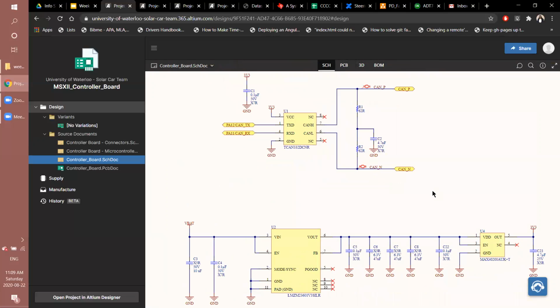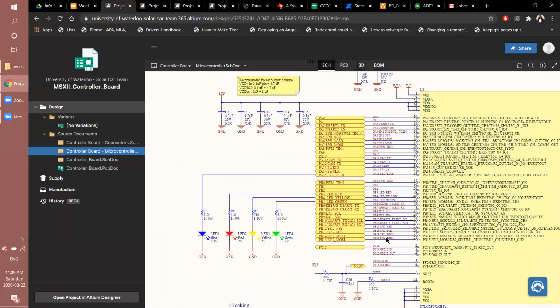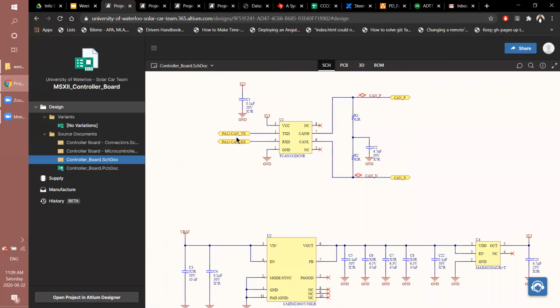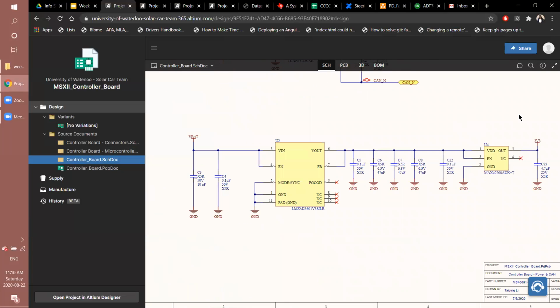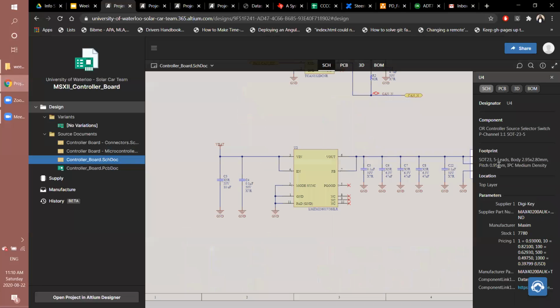And then finally, as I mentioned before, we have our TCAN CAN transceiver. Again, when we're looking at the microcontroller, CAN is routed out as an RX and a TX pin, but then to match with the differential signaling of a CAN protocol, we need the CAN transceiver to deal with that. And then again, as I mentioned, we have our 3v3 converter.